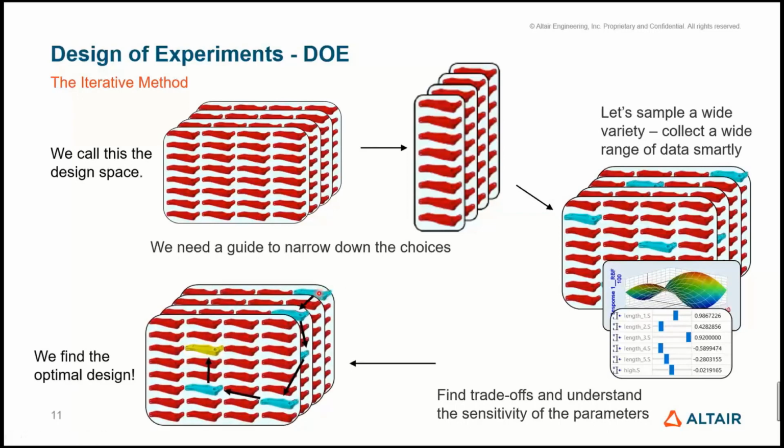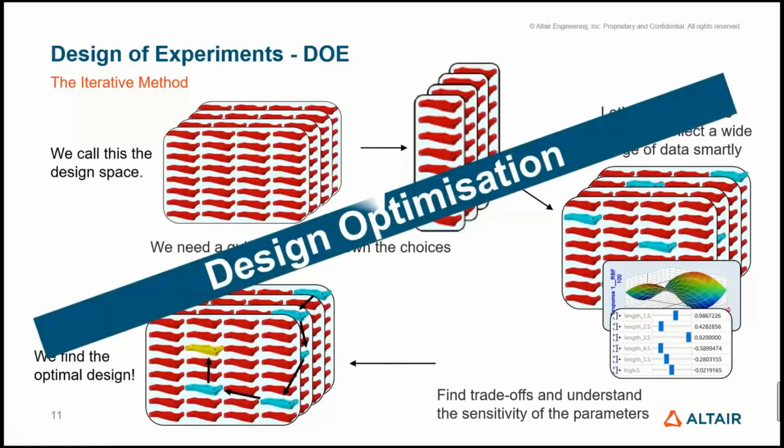And once we start from, let's say, your first design iteration, we change it once, and we actually have a general direction. And through this general direction, where we start meeting all of the performance targets that we need, where it's become even better than our first design, that's where we'll realize that out of this sampling space, you'll be able to find your optimal design. And that's basically what we call design optimization using DOE in a nutshell.